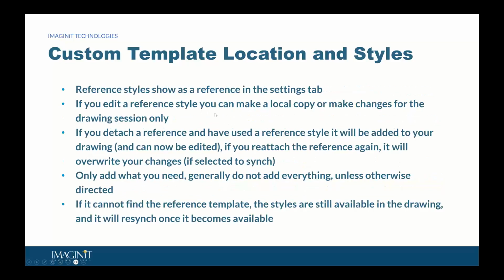And then reference styles will show as a reference in the settings tab. If you edit a reference style, you can make a local copy or make changes for the drawing session only. In other words, if somebody needs to make changes to it, they can make a local copy of it. If you detach a reference and have used a reference style in it, it will automatically be added to your drawing and now can be edited normally. If you reattach the reference again, it will overwrite your changes if it's selected to sync.